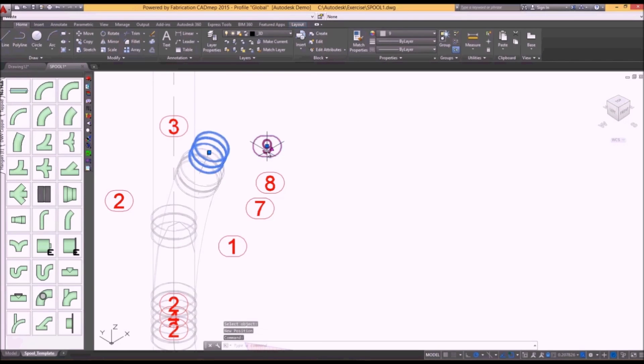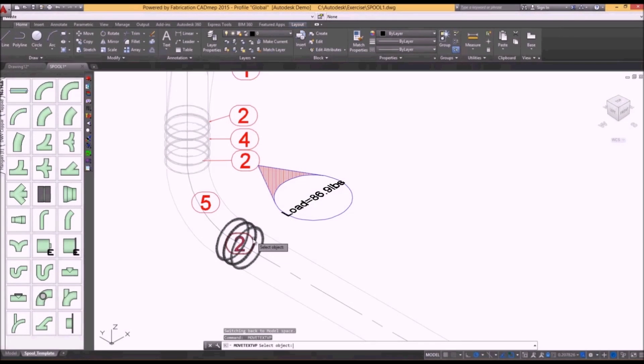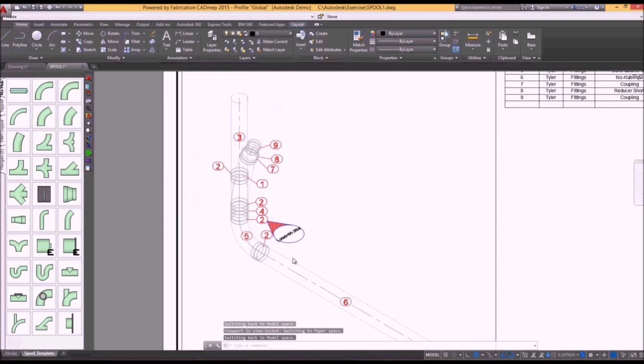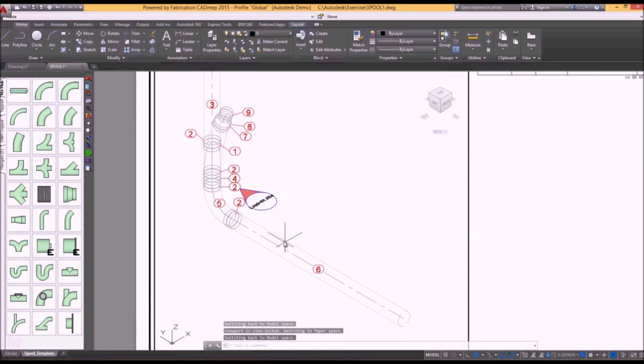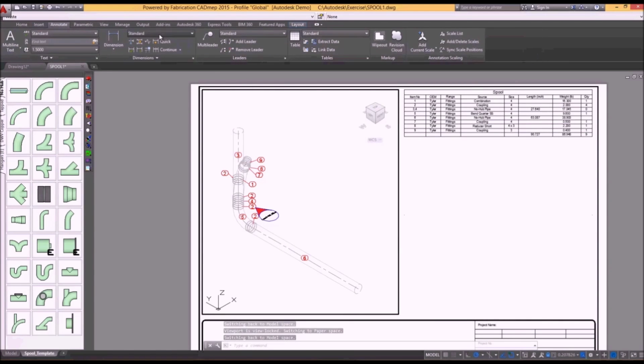So there's a really great tool where you can select the tag and add these leaders to it. So the way we're doing this now, we created a separate drawing with the elements that we selected in the other model. And I'm just going to continue moving some things around. Another way we could do this is we can select parts of our model and just create a bunch of different layout tabs within that same drawing. Just throw a couple of dimensions in here real fast.